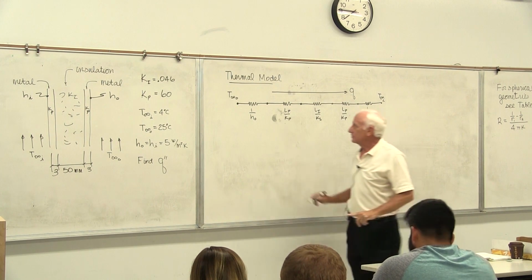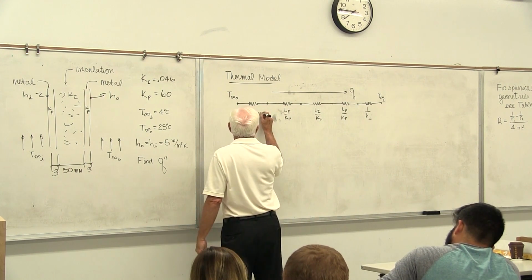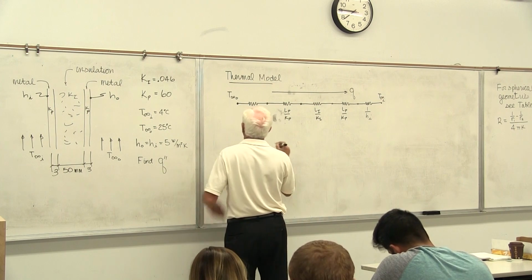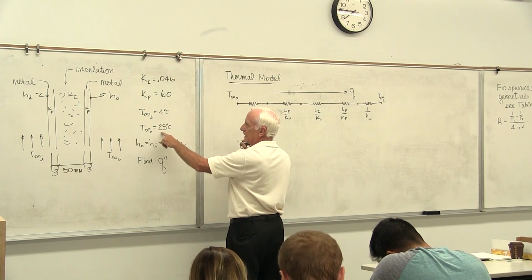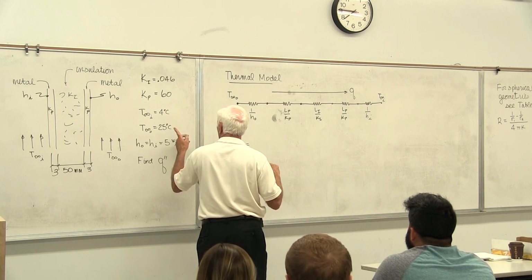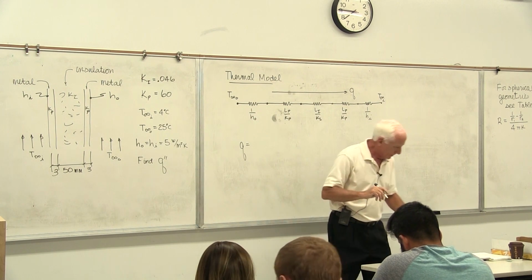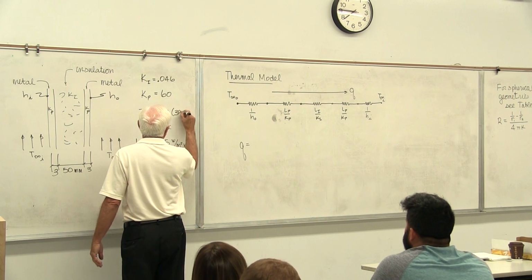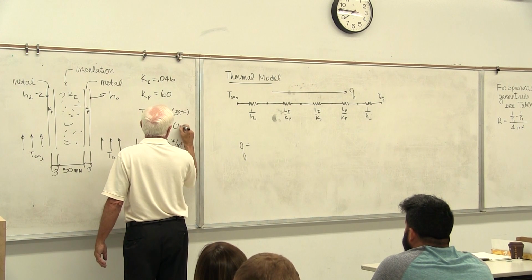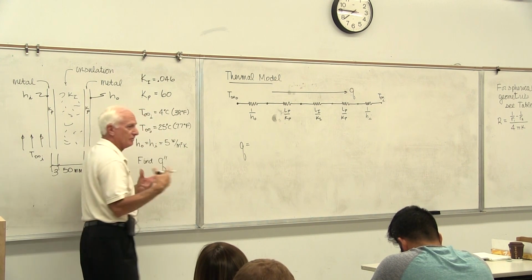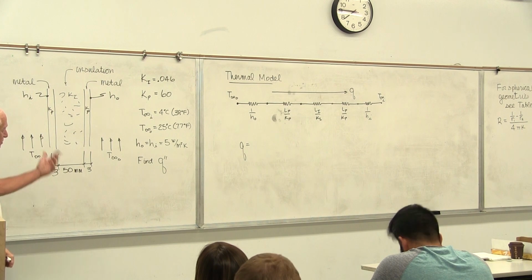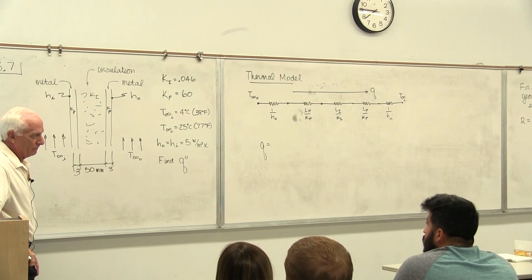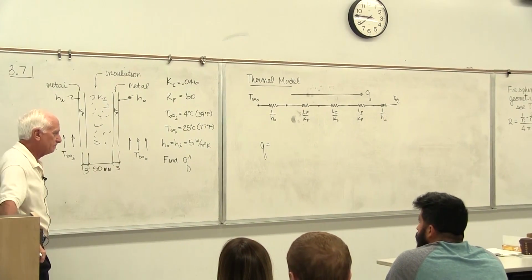All right, so this guy, let's just find Q. Q equals T hot minus T cold. Oh, by the way, these guys here: 77 and 39. Just so you know, 39 degrees Fahrenheit inside, 77 degrees Fahrenheit on the outside. I'll give you some feel for it. The inside of the refrigerator is supposed to be around 39 degrees. That's kind of a standard. Most refrigerators are designed to a standard like that to keep food fresh and safe.